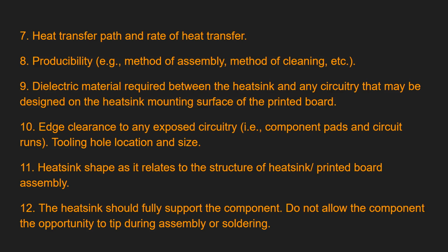Heat transfer path and rate of heat transfer, producibility, which we already talked about in the initial lectures, which means method of assembly, method of cleaning, etc. Dielectric material required between the heat sink and any circuitry that may be designed on the heat sink mounting surface of the printed board. Edge clearance to any exposed circuitry, that is component pads and circuit runs, tooling hole location and size, heat sink shape as it relates to the structure of heat sink printed board assembly.